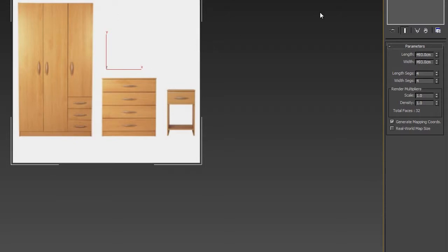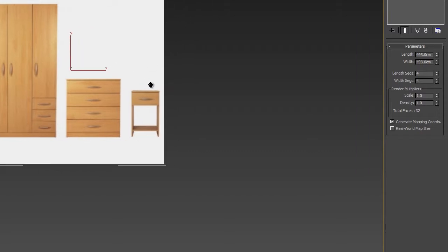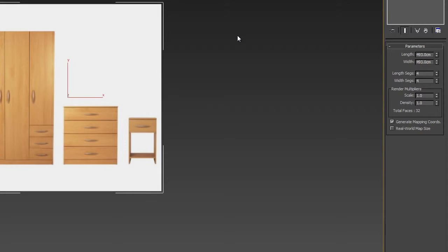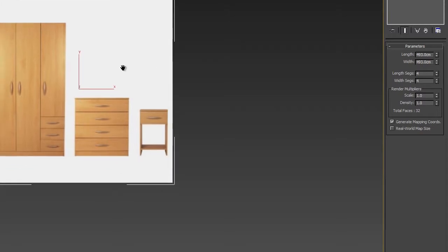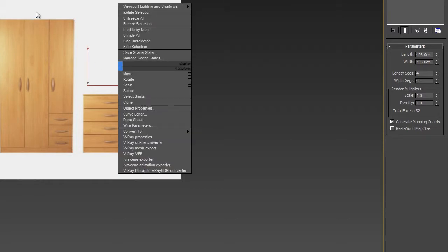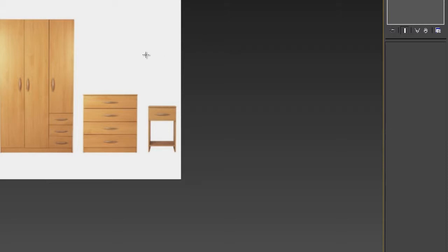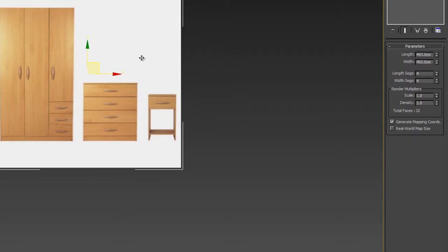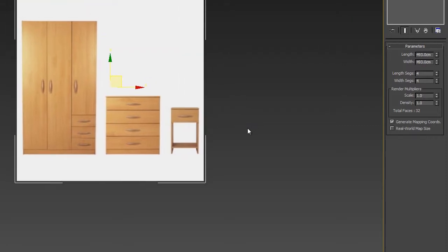So following my tips, we'll start with the middle object. To break this down, the main dominating shape is a box, so we'll start with a box. Before we do that, I would just like to freeze this plane so I can no longer click or move it. And also I would like to zero my reference plane to 0, 0, 0.